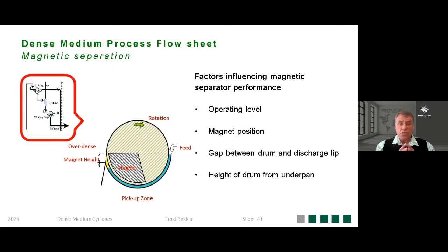Some of the factors to keep in mind, and as I said, there's going to be a more detailed presentation later: your operating level, magnet position, the gap between the drum and the discharge lip, and then the height of the drum.